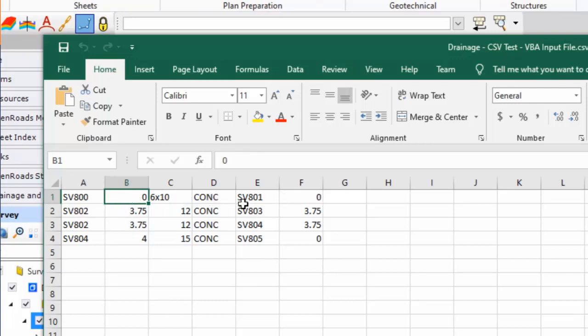So those two actually define the culvert, our 6-foot by 10-foot culvert. If I want that to be annotated as a culvert instead of concrete, I can change this to culvert here. Then the next is, again, point pairs: point name, the dip at that point, size, material, connecting point, and the dip there. Our last one is our point pipe inlet or outlet, so it has a dip of 0. The elevation was taken directly at the invert of the pipe.